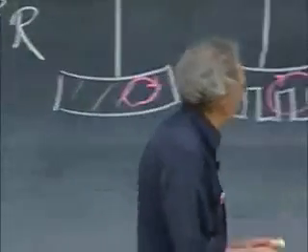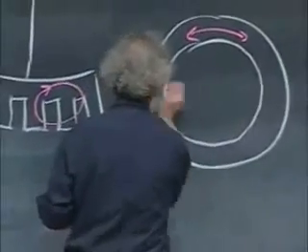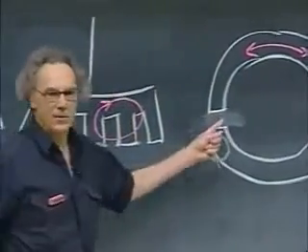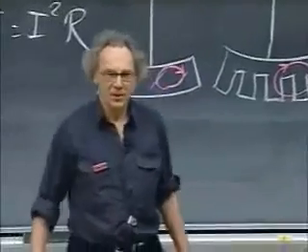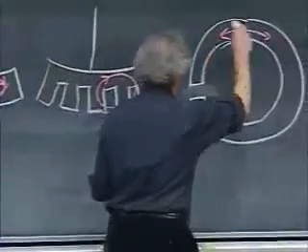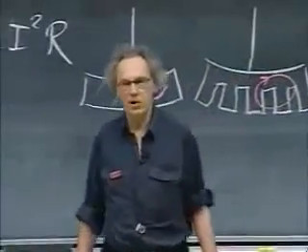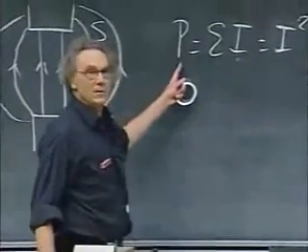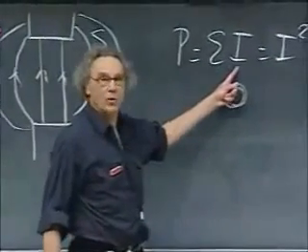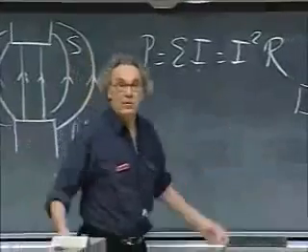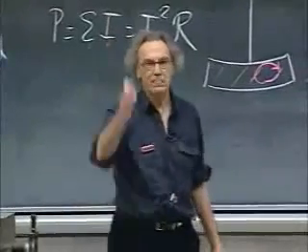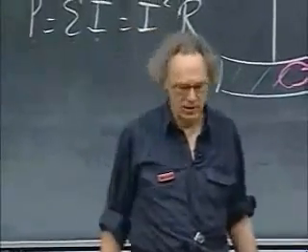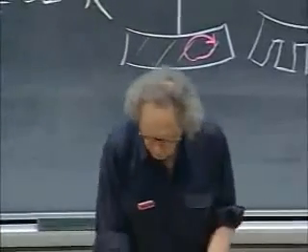And then I will throw through there another ring, which is the same dimension, but this ring has an opening here. Air, the resistance is huge. So the current that is going to flow, this eddy current, is way lower because the resistance is so high, and so there is no power dissipation because I is so low, and so there is no heat produced at the expense of kinetic energy, so there's no damping. There is no strong force that opposes it. And I can show you both.